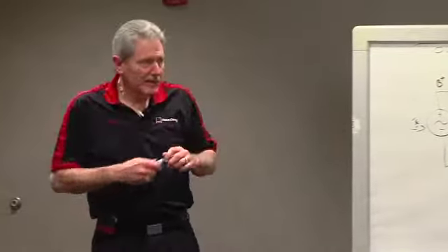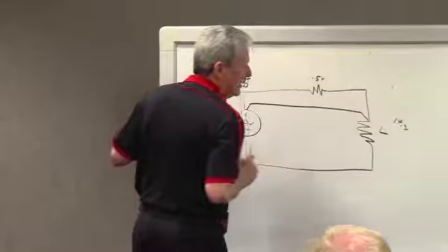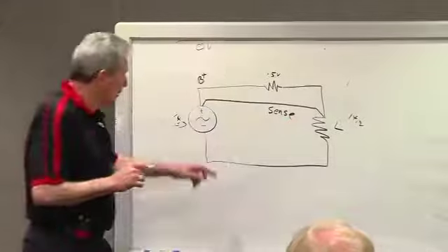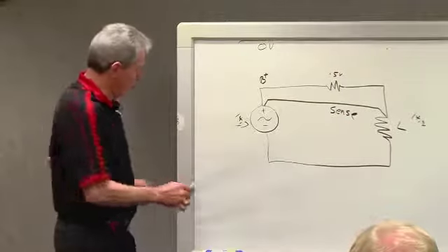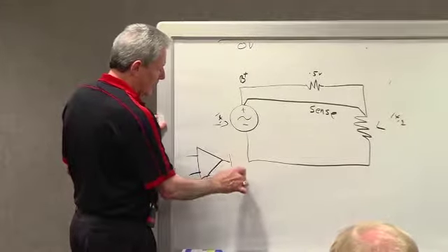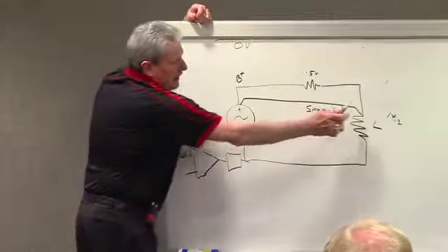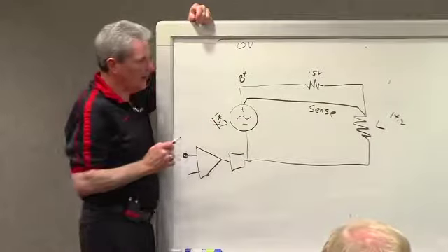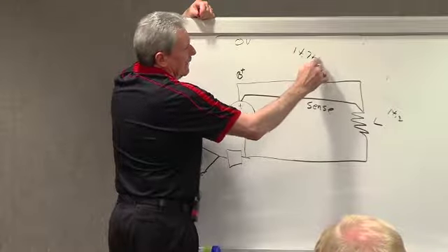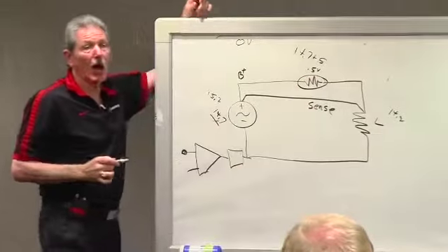Okay. So the way to solve that is to run another wire to run that sense into the comparator. Remember I showed you they had the comparator, and then this went into a PWM, and that went into the MOSFET. So now this is going to connect to here. So this is set for 14.7, so this will be 14.7 plus 0.5. So this will go up to 15.2, and it will compensate for that loss.